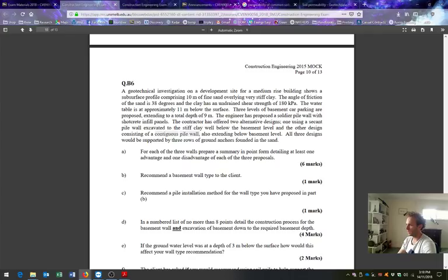So let's start the question again. Referring to W2 lecture content, they use D-wall for 2-level basement when there is sandy soil there. Yeah, you're right, they did too. I remember now. Well, I guess it would be based on the client too, and how important it is to have a really waterproof seal. So if it's just a car park, it might not matter that much that they get a little bit of water leaking in. If it's maybe something of higher value, a lecture theatre, a cinema, then maybe they say, right, we don't want any water in there, so a D-wall would be appropriate. So you're right. You could recommend a D-wall, but you'd have to put a proviso of depending on the client preferences.